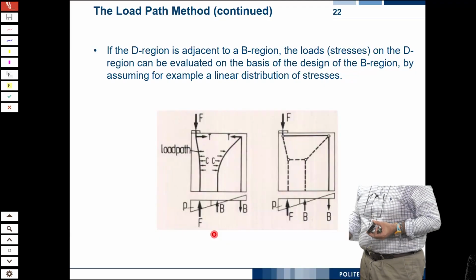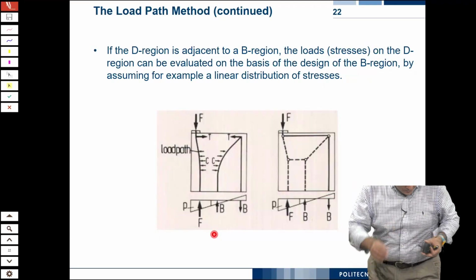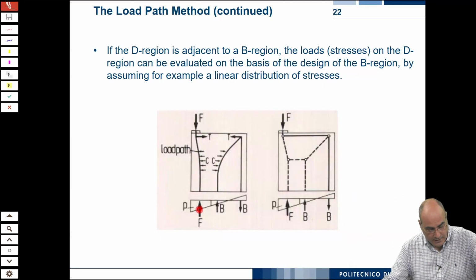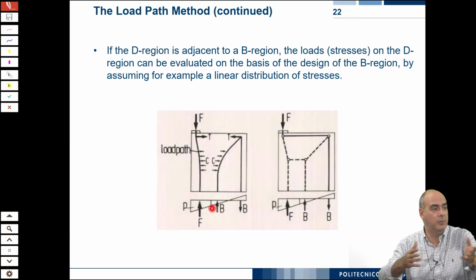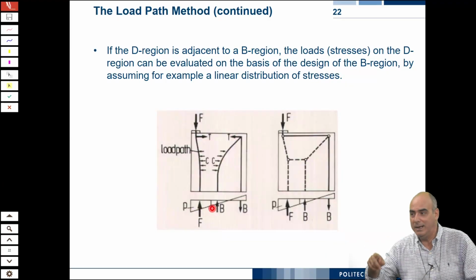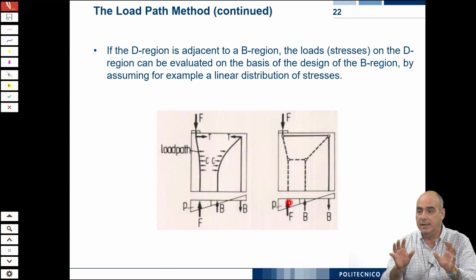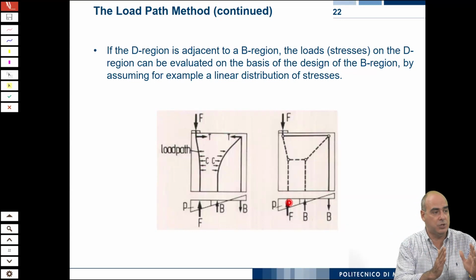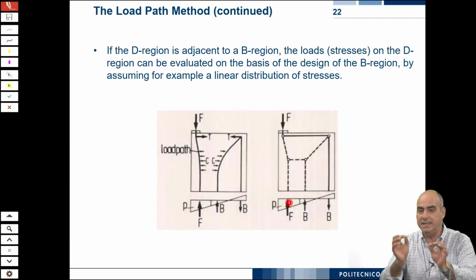Anchor block is eccentrically loaded, that is what you have to deal with. And so, if you split your stress diagram, this is the stress diagram, which comes with the same formula that we have seen yesterday, N divided by A plus M divided by the flexural modulus. But we have split our diagram into a part which carries the axial force and a part which carries the bending moment. And we have these resultant forces.